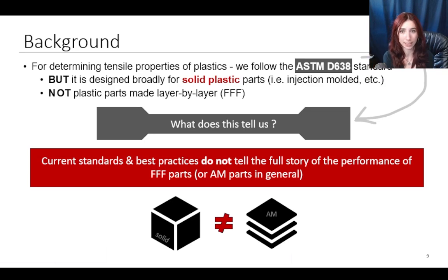So what does this tell us? It tells us that current standards and best practices do not tell the full story of the performance of FFF parts, or even AM parts in general. A solid part made of solid plastic is not the same thing as a plastic part made by layers.